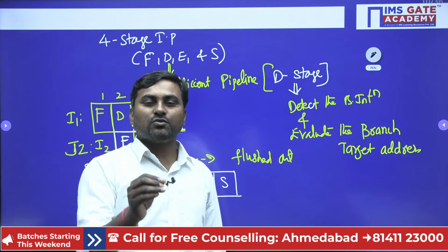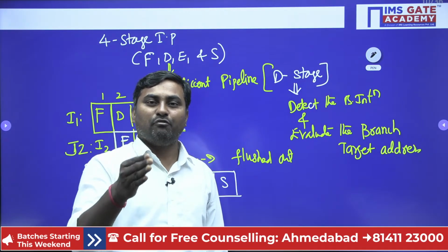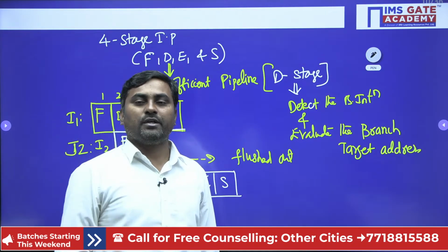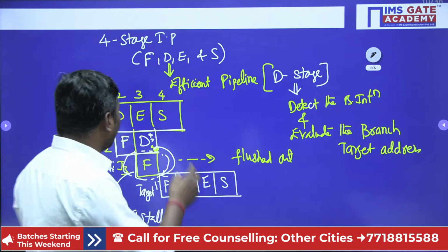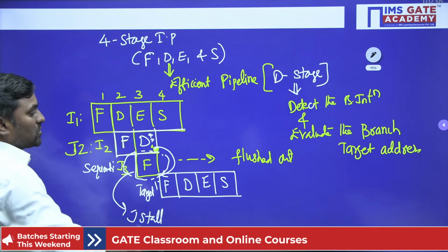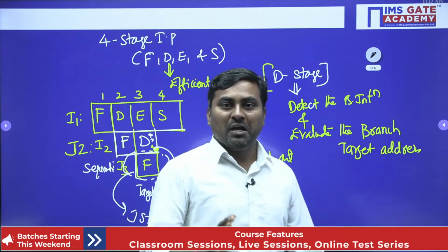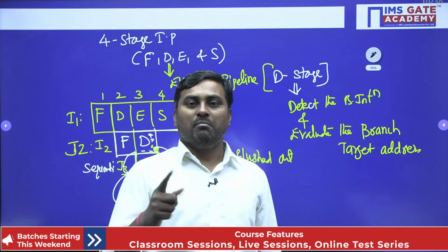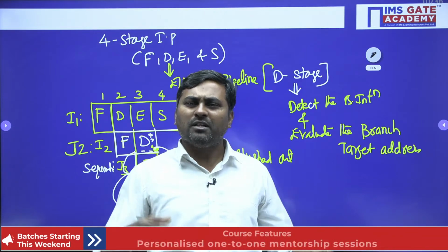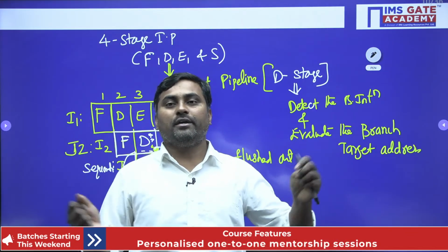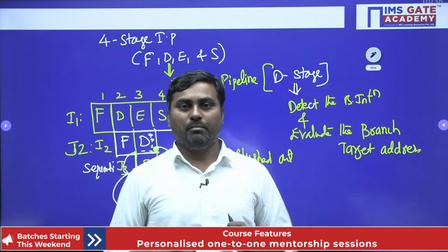Based on the instruction pipeline, stalls can vary from 1 to k-1. The best case will be 1, the worst case will be k-1, because we modified which stage? The decode stage we modified. So now 1 stall is wasted here. Is it far better than the multiple pipeline? Multiple pipeline is fast, but the hardware cost is duplicated here. 2 pipelines are required to implement.